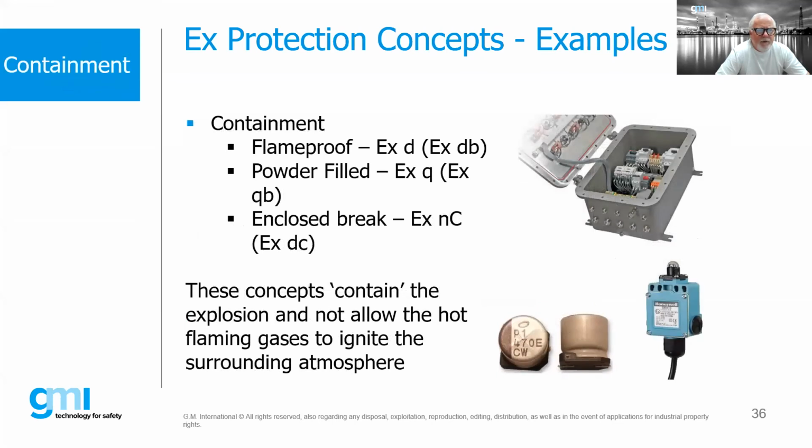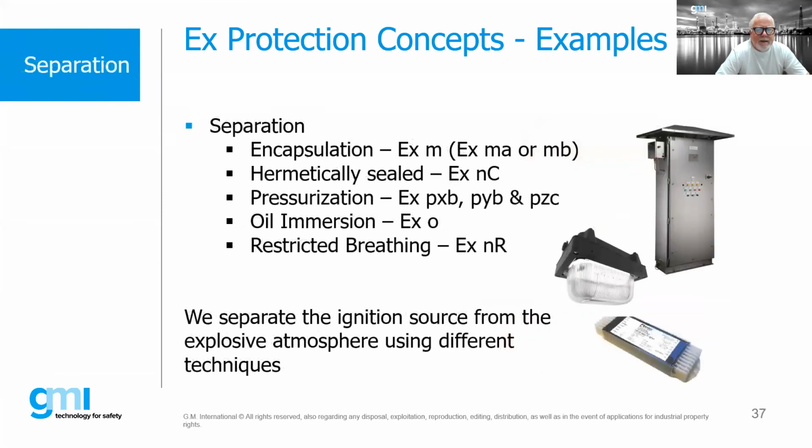Containment, again, flame-proof. We also have powder-filled enclosures. They contain the explosion and do not allow the hot flaming gases to ignite the surrounding atmosphere. So this is very commonly referred to as EXD. And then separation, again, we could do encapsulation, hermetically sealed, pressurization, restricted breathing. So all of these protection concepts are used in industry. Some are more popular in some parts of the world or for certain applications.